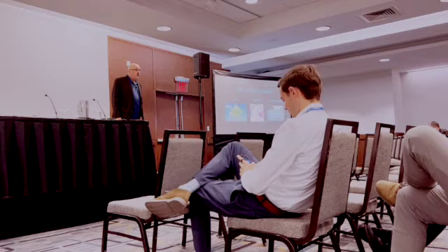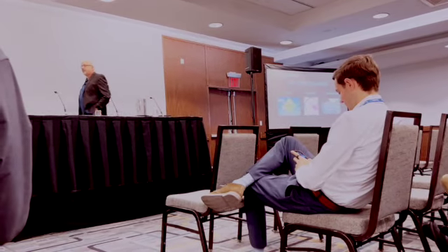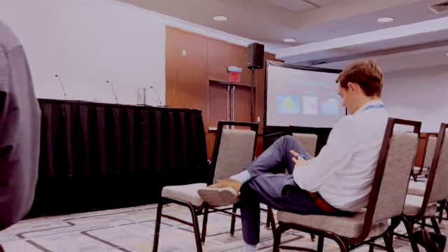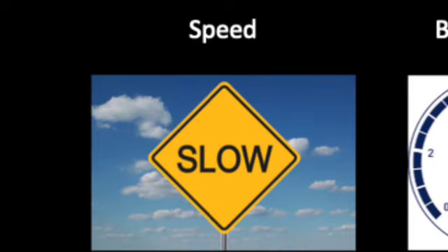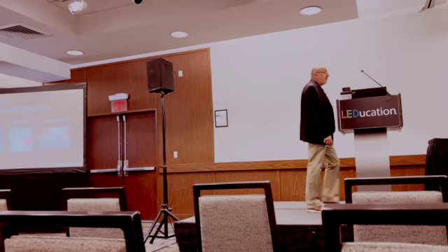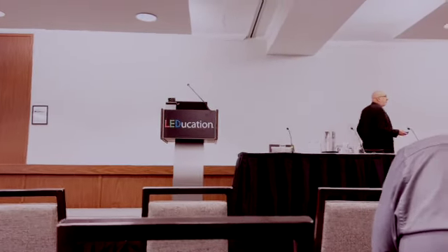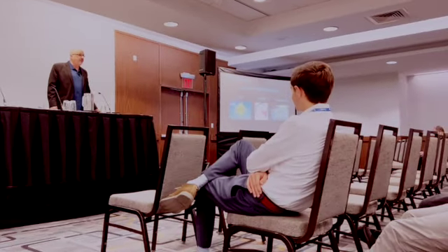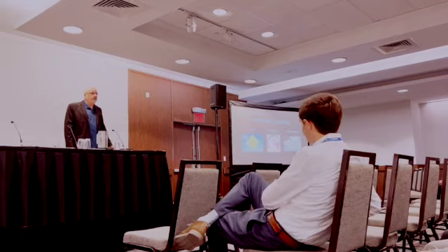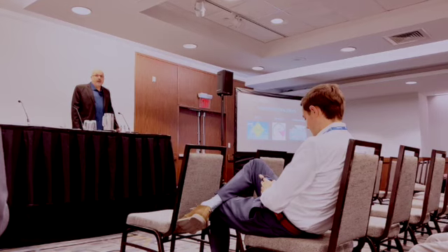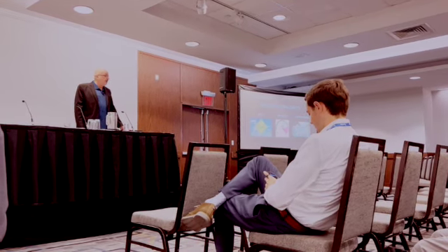Okay, so what's the catch? So the catch is there are some challenges with this. It's a little different from Bluetooth. Number one, it's a little slow. So imagine that we're operating at 60 hertz, which is what power in the United States is, 60 hertz. There's only 2 half sine wave cycles that we can use for a message in every cycle of that 60 hertz, so we can only send 120 bits per second across this. Now that's really all we need.